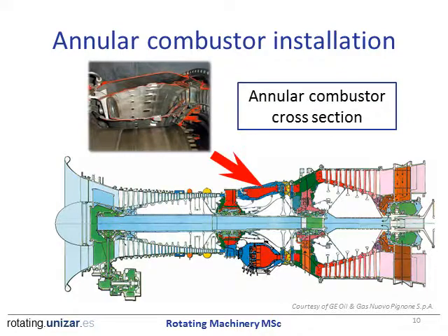On here on top, this red area is where the combustion takes place. If you look at the top and the bottom, the reason they look different is that this is what is called a single annular combustor, and this is a dry low emissions combustion system. So it's not that on the same turbine you have both. You have either this type or this type. It's just for the sake of clarity, we wanted to show these two types of annular combustors in a single shot.